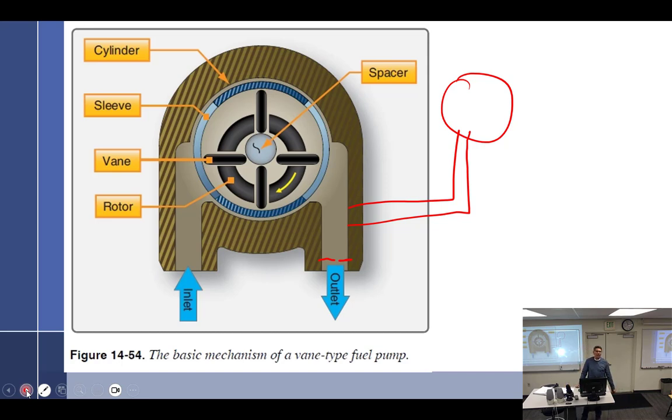I'm going to reach over and turn on the electric pump, also called the boost pump. And I'm going to watch fuel flow, because all these engines have a fuel flow gauge. I'm going to watch the fuel flow gauge, and it's going to do nothing. Then it's going to start rising. As soon as it starts rising, I shut off the pump. So right there, I was dumping fuel into the engine. Because you can do that. You can override the whole fuel system and just dump fuel right into the engine. And it's not an updraft, these things. The fuel injectors are actually on top of the engine, spraying into it. So there you go. Put a bunch of fuel in the engine, then hit the starter.